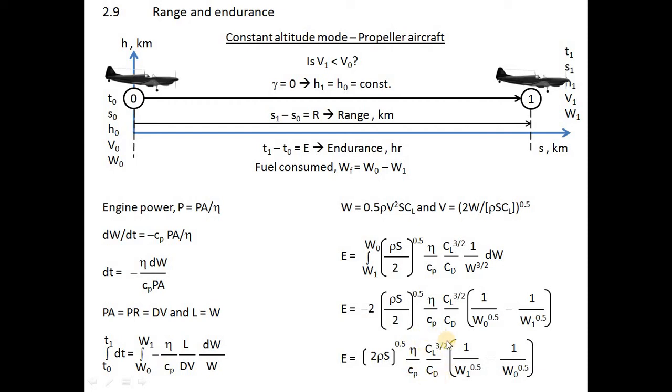You have to fly at this, number one, to gain the most endurance and fly the longest time. Number two is to have as high a propeller efficiency as possible. So it's good to have a variable pitch propeller so that you can adjust the propeller pitch to give you the most efficiency. And of course the engine must also be mechanically very efficient.